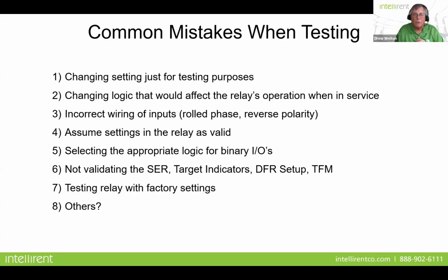Changing the logic that would affect the relay's operation in service. And what I mean by logic is if you have an element sensitive to breaker position, but you're not simulating the breaker during the testing process, you may disable the breaker supervision. That's not a good thing. Incorrect wiring of inputs, rolled phases, reverse polarities. Assuming the relay setting is valid.